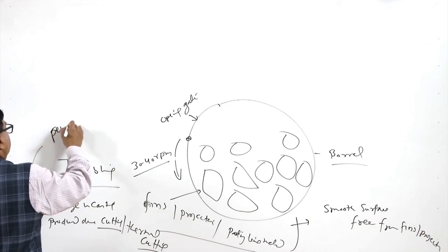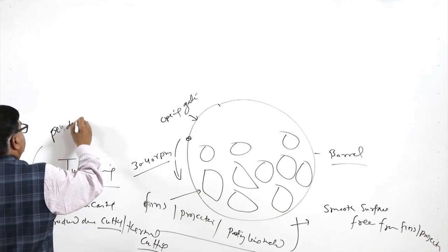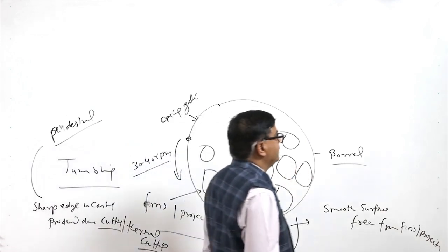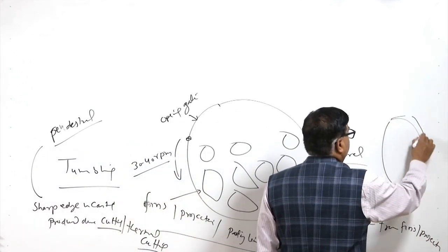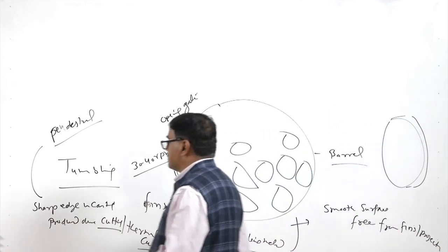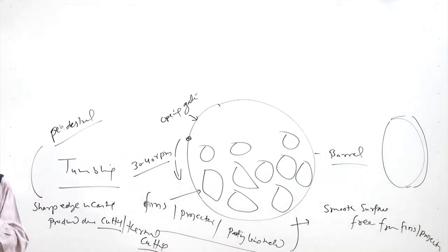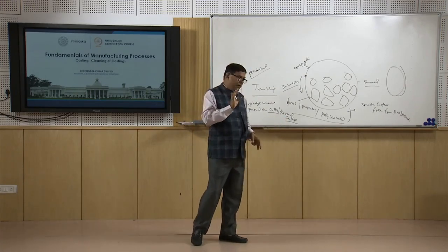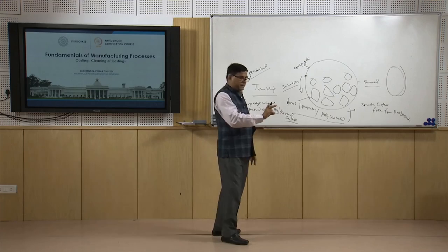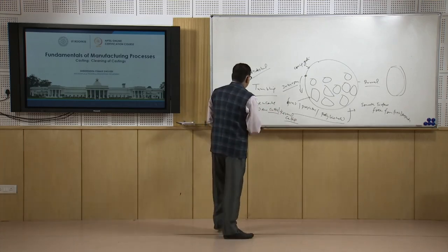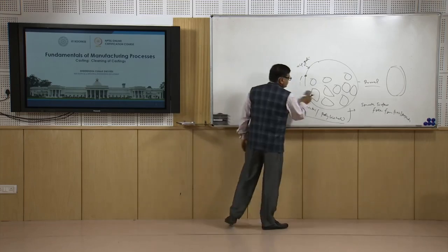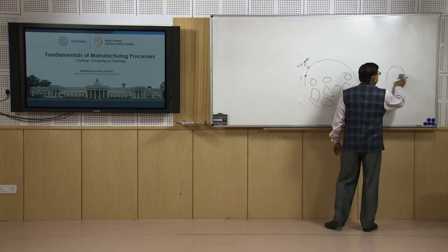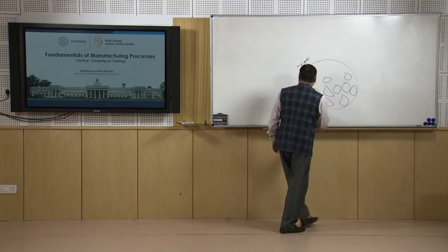either, depending on the size of the casting, a pedestal grinder for the small size castings. Basically the casting is held in the hand and it is pressed against the rotating grinding wheel. Another method is that if the casting is really big in size, then the swing type of grinder is used, which is pressed against the casting. It can be moved easily and brought near to the casting, and it is pressed against the surface which is to be smoothened or finished. So, these were the different things related to the cleaning of the casting, and the entire steps